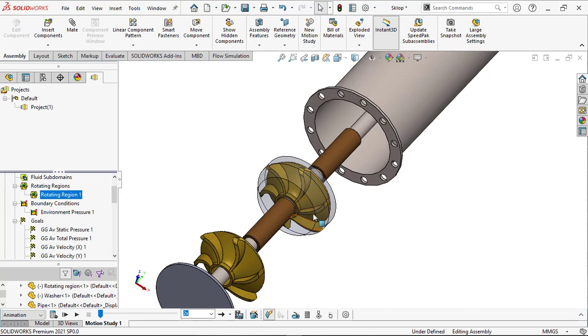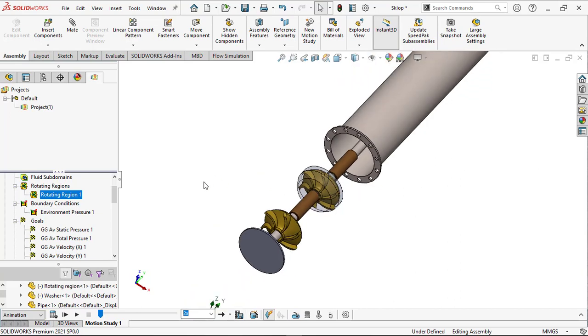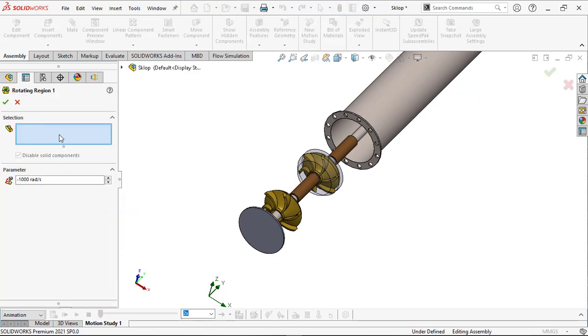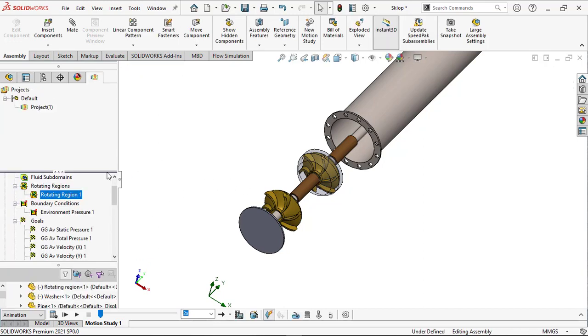Okay, and this region you need to rotate with respect to the rotating region by selecting this CAD part into account. Okay, so whatever is covered inside the portion will be rotated by selecting these two rotating CAD models. I have previously defined it, you don't need to worry about it. The angular velocity I have defined is minus 1000 radians per second, anti-clockwise, minus sign. Okay, so once you define these, you can directly go ahead with the boundary conditions.